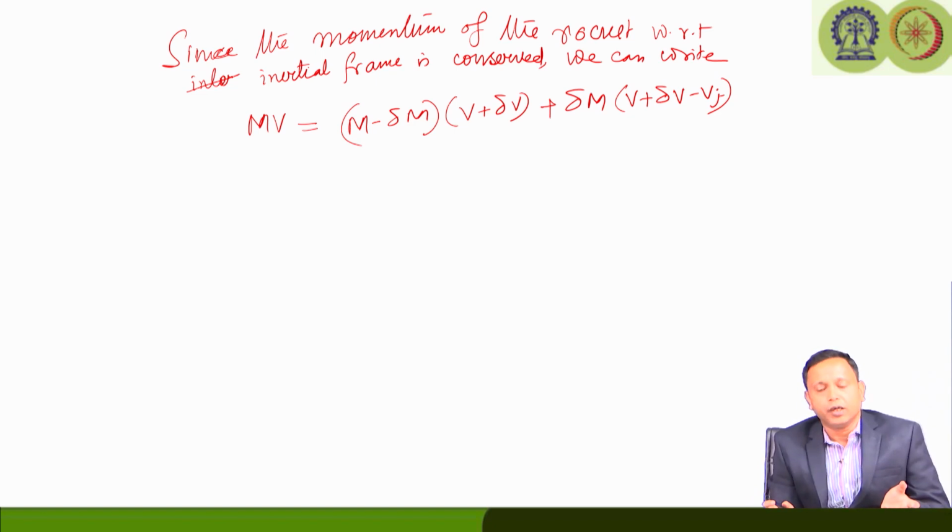What exactly is it doing? If you look at the principle of generating thrust, it is nothing but ejecting out its stored mass. For example, a solid rocket burns fuel and oxidizers, and the combustion gas comes out through the nozzle, expanding and generating a high velocity jet which produces thrust. In a liquid rocket, it burns liquid fuel and liquid oxidizer in the combustion chamber, and the product gas expands through the nozzle and generates a high velocity jet which in turn produces